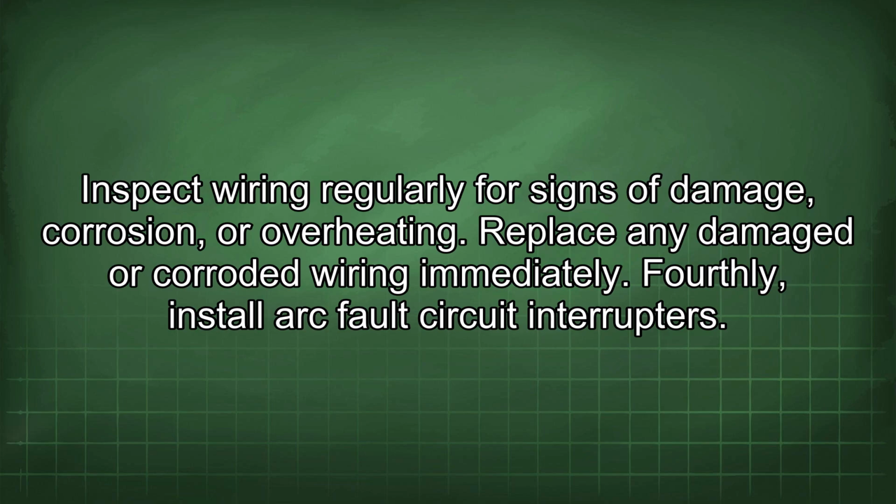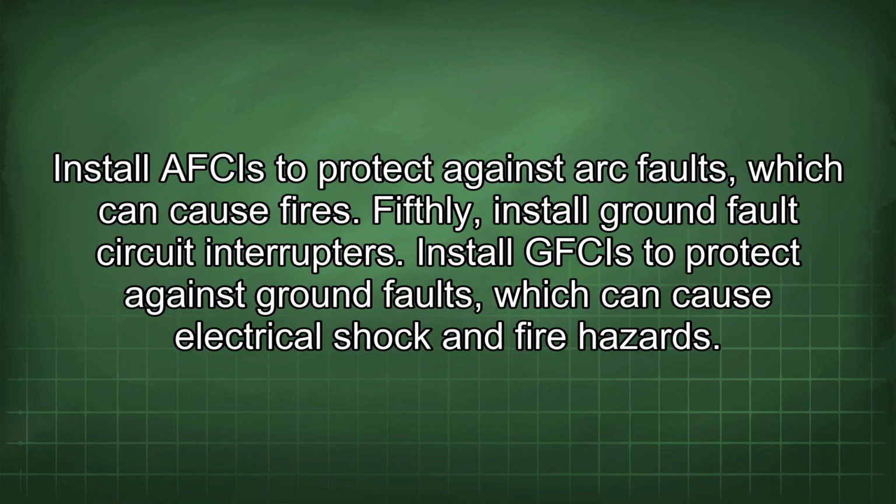Fourthly, install arc fault circuit interrupters. Install AFCIs to protect against arc faults, which can cause fires. Fifthly, install ground fault circuit interrupters. Install GFCIs to protect against ground faults, which can cause electrical shock and fire hazards.